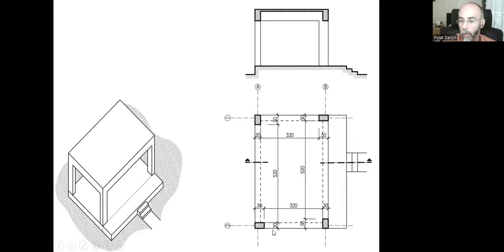And I need to do the other direction for the columns, start with 30, and this time it's 520 centimeters and 50 centimeters and 30, 520, and 50. So all the columns can be created because I have the sizes of all four columns and their gaps. So if the builders start from this column, they're just going to create a 50 by 30 centimeter column here, and then they are going to leave a 320 centimeter gap in between and create another